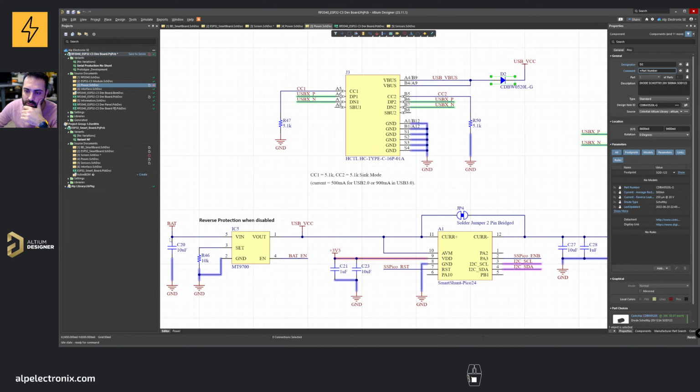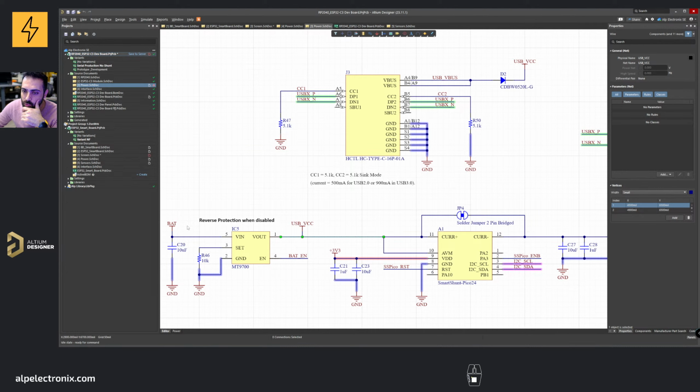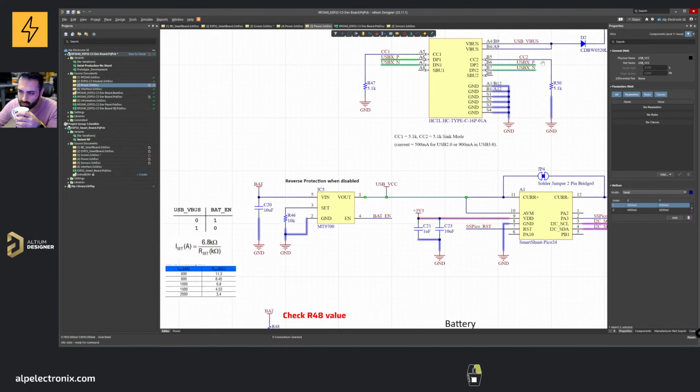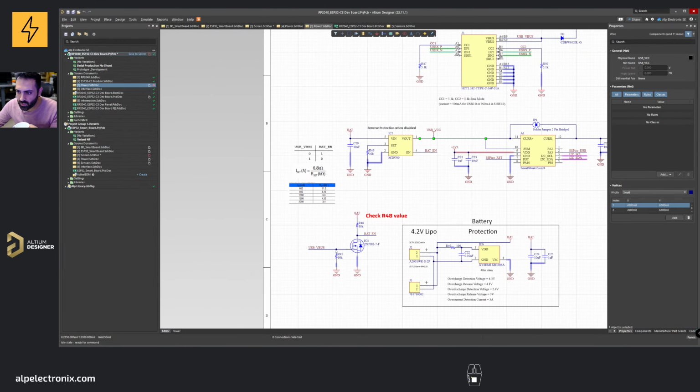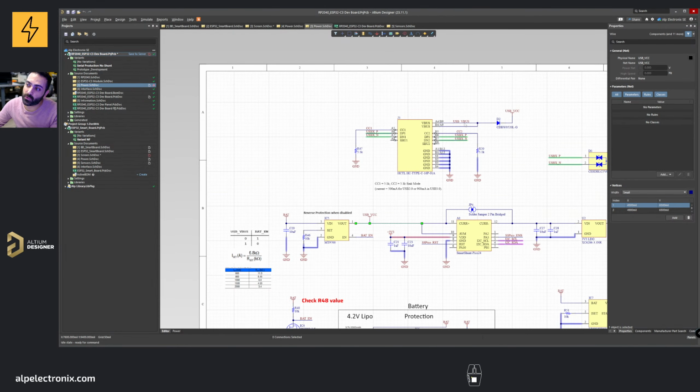So when you power the LDO from battery, this line is then the battery, when there is no USB VCC, or when the USB is not connected. But this is a bit tricky because the other parts are getting power from USB VCC, and what you need to do is just block or limit the reverse current, so there is no voltage on this bus, because this one is directly connected before the diode.